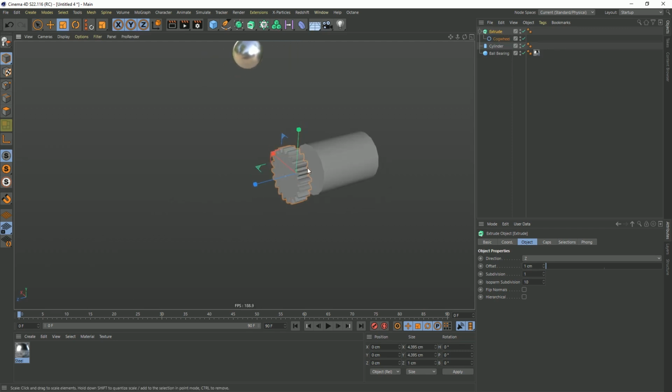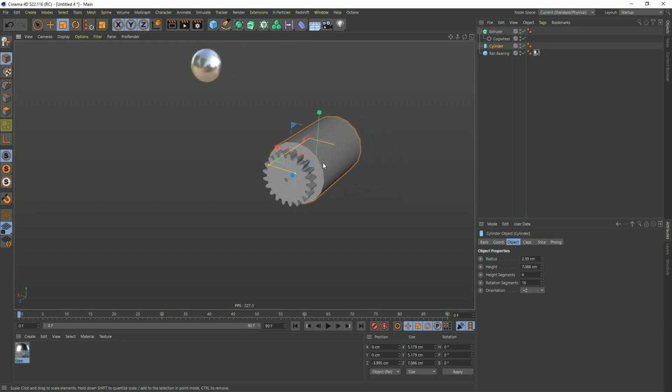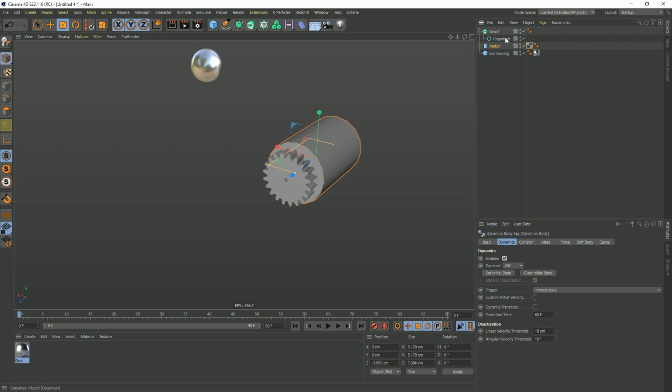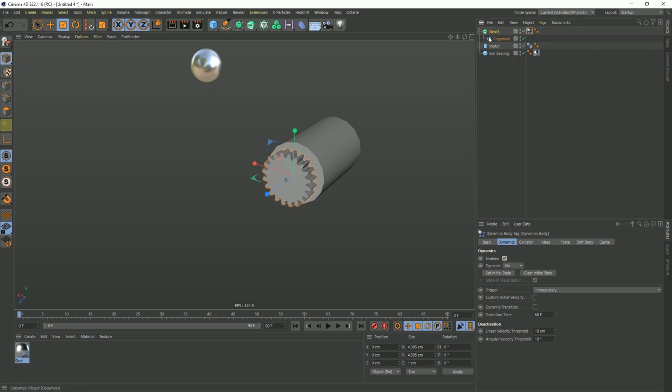Now that we're seeing our base gear scale, this motor back here can be scaled up to whatever. This is really just a visual. So that will be the motor that's counter rotating on this shape. Let's just start right away by making it dynamic. To stay organized, rename the cylinder motor, and this extrude, name it gear 1. And this motor, technically it can be dynamic, simulation, collider body. So it's dynamic, but it's not moving anywhere. Then on the gear, right click and add the simulation rigid body. These are both dynamic objects.